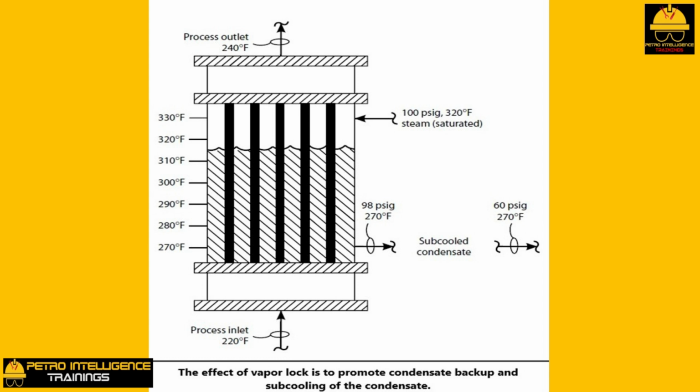Option 3, inject cold water into the condensate rundown to suppress vaporization. To suppress vaporization of 320 degrees Fahrenheit condensate, as shown in this picture, enough 70 degrees Fahrenheit water, that is, 25% of the condensate flow rate, would have to be injected. This will also give good results. Option 4, drain condensate to the sewer beneath the reboiler. This unfortunate option is, by far, the most usual solution.